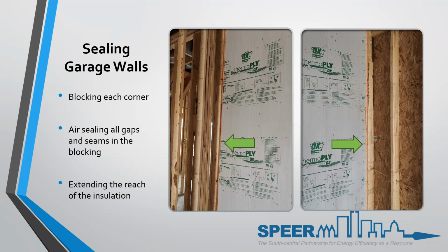Again, I'll keep reiterating the same thing: these walls, in my opinion, are exterior walls. And yes, this is going to be sheetrocked, but sheetrock by itself is not an air barrier. I mean, the material itself is, but the way it's installed leaves gaps. It's been proven before. That's why you have a gasket or caulking at the junction of the top plate: sheetrock isn't perfect, wood isn't perfect. There's not a nail every 1 inch to close the gap. It's actually 16-inch on center, or 18-inch, or sometimes even 2 feet on center across the top plate, leaving a bowing effect in between, and you can slide a credit card in between. Putting a gasket there closes those gaps.